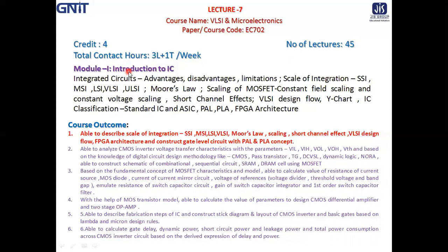In Introduction to ICs, we will be studying about the ICs, advantages, disadvantages, limitations, scale of the integration, SSI, VLSI, LSI, ULSI, then Moore's law, scaling of the MOSFET, constant field scaling and constant voltage scaling, short channel effects, VLSI design flow, Y chart, IC classifications, standard IC and ASIC, PAL, PLA and the FPGA architecture.